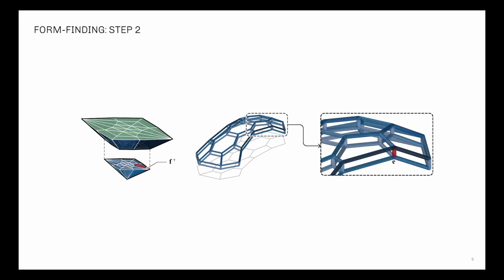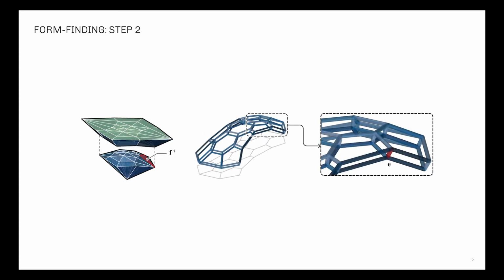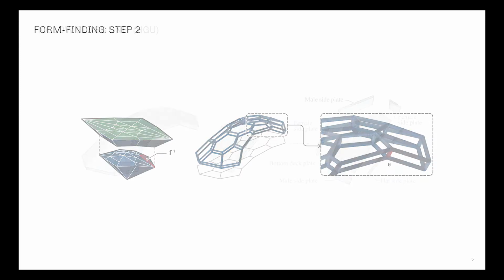After having the single-layer funicular form and force diagrams, the double-layer form can be derived by subdividing the force polyhedrons of the single-layer form. The force diagram is subdivided in a way that all the interfaces between the polyhedral cells are as perpendicular as possible to the force flow, so the sliding can be prevented.